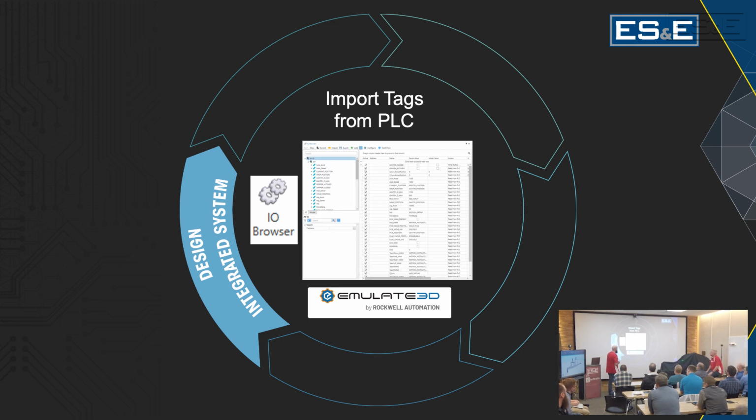So what you do is you pull that PLC in using the I/O browser I just showed you, and then you can import all the tags that are in the program. They just all import and pull into your Emulate3D program, and then you can tie those tags to specific components. In this case, we're using a distance tag.